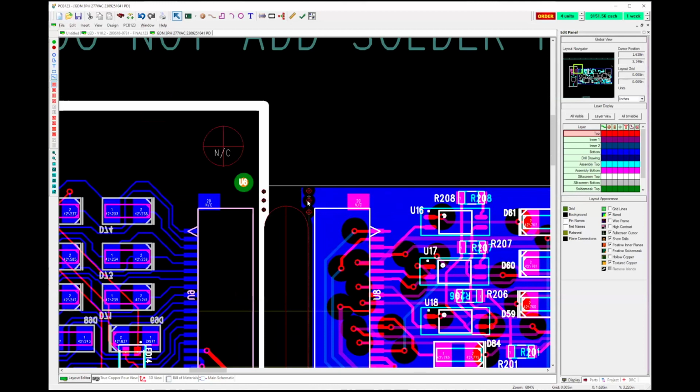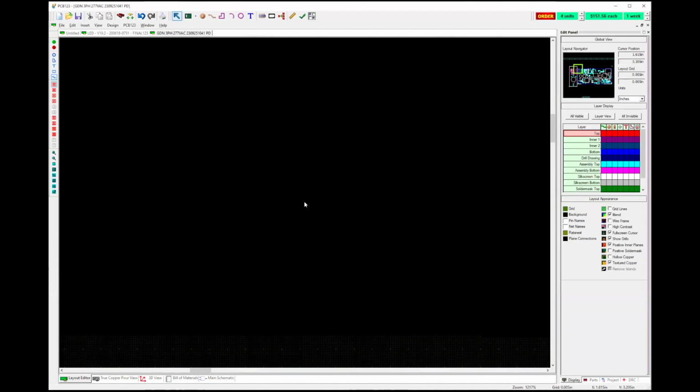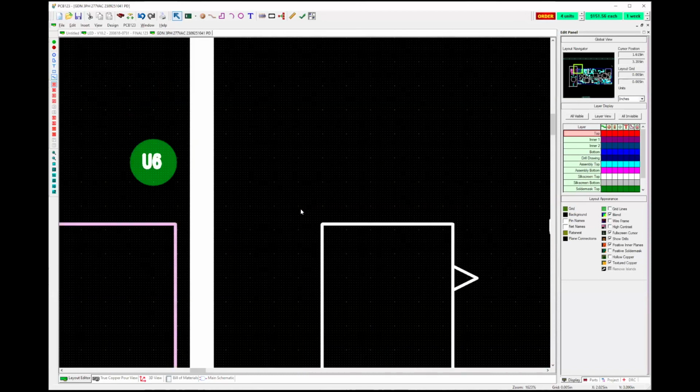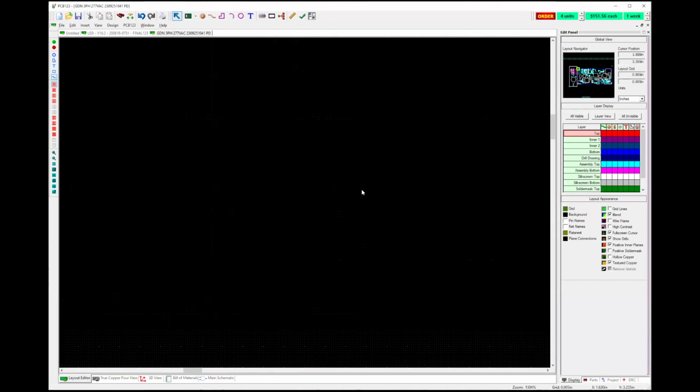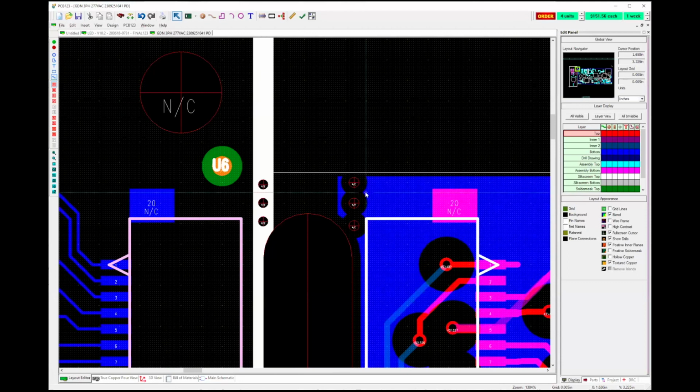You want to make sure that they're far enough apart that they can be manufactured. If they're too close together, they'll just delete the drills because they're too close together. They'll snap drill bits, and they won't give you those holes. So I think the rule is 10 or 15 mils apart for any holes. If you make them that far apart, you'll be pretty safe.